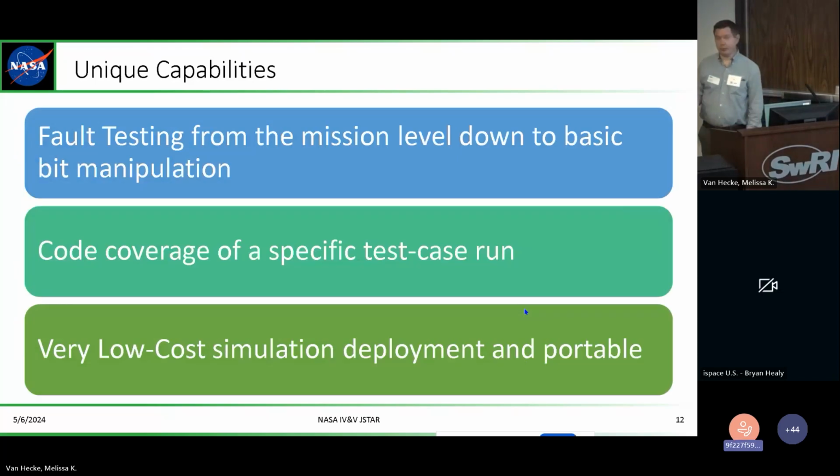So what can we do special being in this all-software environment and on a single laptop? In IV&V, we don't look so much at the happy path of the flight software because we know everybody's testing the happy path. What we really focus on is the faults. If something goes wrong at T+2 and we're just clearing the pad, can we abort the astronaut safely at that point?